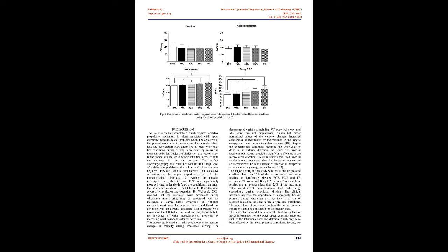After practice, participants performed 5 randomly selected measurement trials. Each subject was asked to drive the wheelchair for 30 m on the pathway at their self-selected speed under different tire air pressure conditions. To avoid the effects of acceleration and deceleration on the measurements, the 2 m at the beginning and end of each trial were excluded.